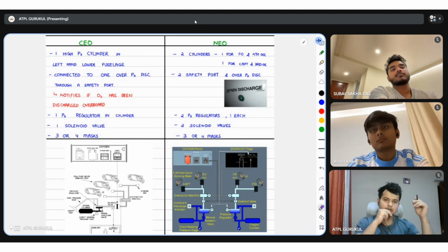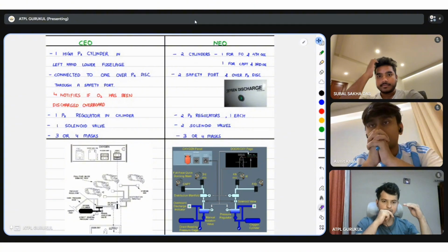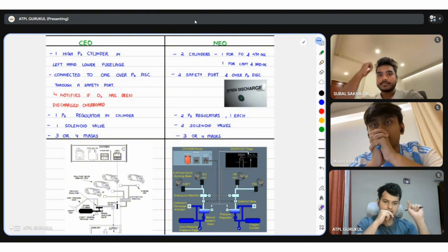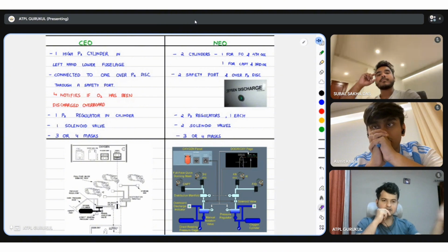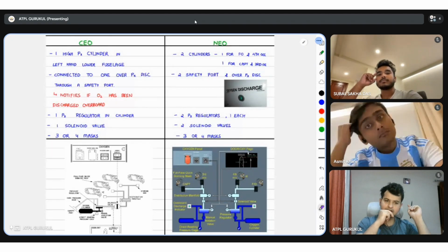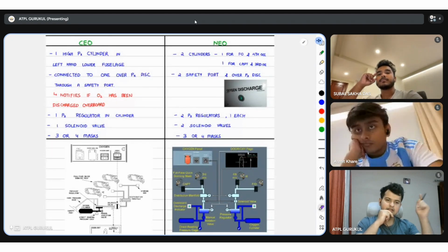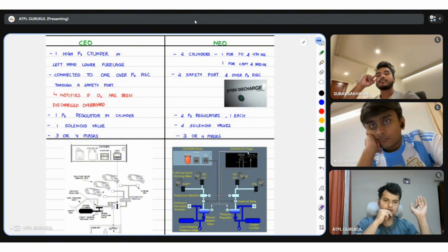When you are in cockpit preparation, you are required to turn all the lights to auto position, lights out position, right? In this, the crew oxygen masks are also in off position, and you turn them on. So when you're securing the aircraft, you do not want the oxygen cylinders to be continuously connected to the oxygen mask. There can be some minor leak here and there which can deplete the oxygen. Why do you want to waste it? So there is a panel above using which you can shut it off. Lastly, this same one oxygen cylinder can be connected to 3 or 4 masks.